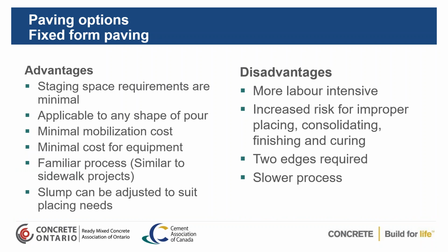So what are the advantages of a fixed form operation? Well, staging requirements are minimal. This is when you're doing smaller jobs that you don't want to bring in a big slip form paver for. It's applicable to any shape or core. If you have islands that you have to work around, if you have obstructions that you have to work around, this will be a very easy way to do that by doing the fixed form process. You have minimal mobilization costs.